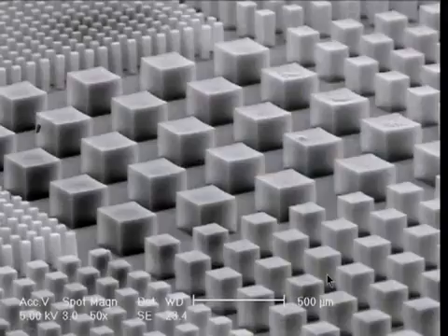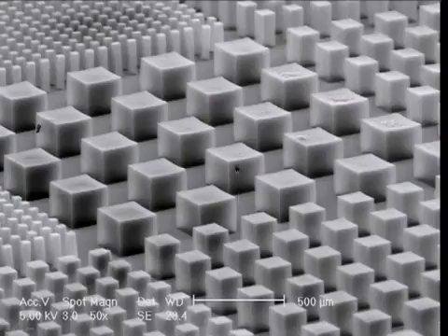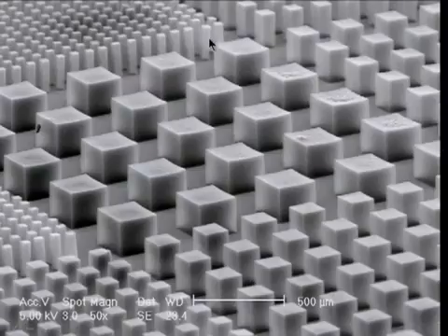So here's an SEM picture of an array of patterned vertically aligned carbon nanotubes. We'll see how these grow later, but here we've used optical lithography to pattern a catalyst, which we then put in a hydrocarbon atmosphere, and the nanotubes grow up, kind of like little buildings. And one of the important things to note about scanning electron microscopy is how the interaction between the electron beam and the sample creates a kind of lighting effect. It looks to me in some ways like there are spotlights over here, but it's totally dark in there, and light wouldn't make a difference. It's the way the electrons interact with the sample that causes these kinds of shadows.